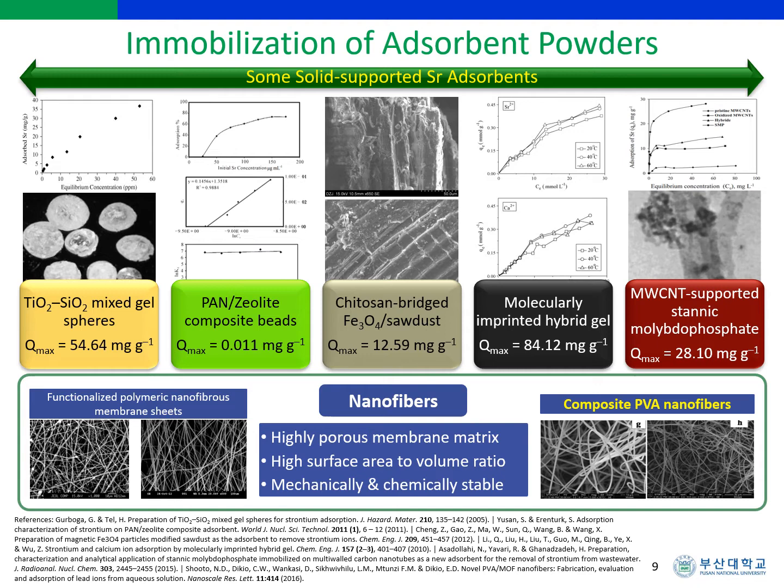The use of nanofibers as a solid support for powdered adsorbents has gained a considerable amount of attention in water treatment, owing to the following features. First, large surface area to volume ratio that can provide higher accessibility of adsorbent sites to the target pollutant. Second, nanofibrous morphology that is favorable for the protrusion of adsorbent particles on the fiber surface, which increases the exposure of binding sites.